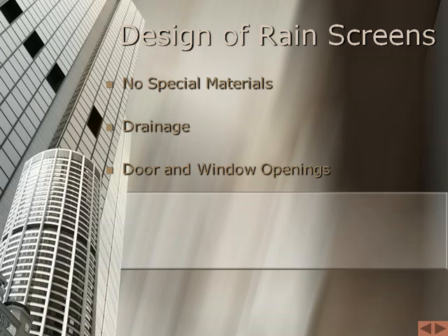In North America, the performance of rainscreen walls has been studied for about 4 decades. No special vapor retarder was installed in the buildings to control movement of water vapor from the inside to the outside, and there appeared to be no harmful effects of condensation in the walls. When high relative humidity is maintained in a building, however, and the outside air temperature is very low, as may be the case in many areas of the country in the winter, there is danger of condensation of water vapor within the inner wall and of frost action. Under these conditions, it is prudent to provide continuous vapor retarder protection to the inside of the rainscreen walls.